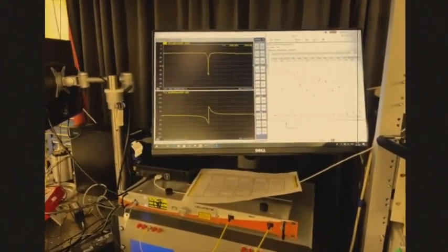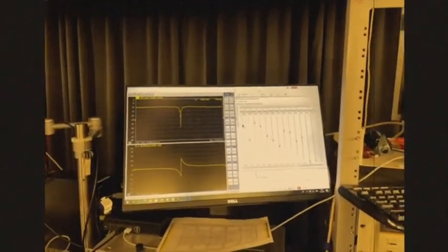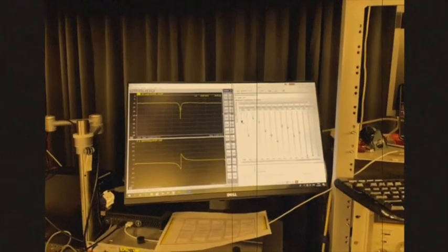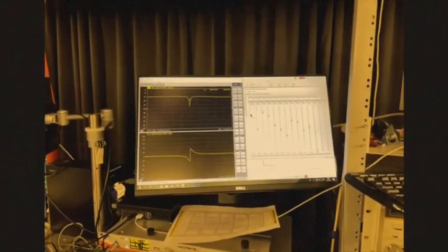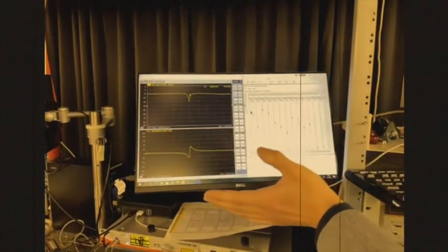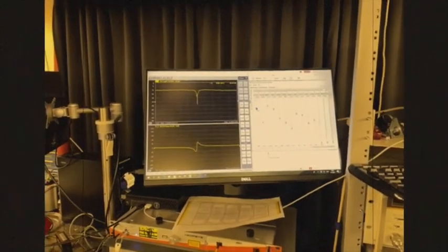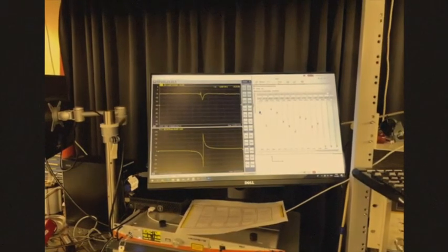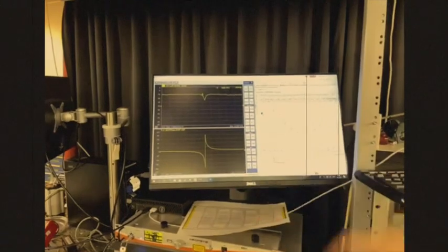And we can see if we change the coupling of our ring resonator, we can change the amplitude response and also the phase response. You see, now the notch becomes shallower and shallower. This shows the potential of the reconfigurability, or the programmability, of our photonic chip. Also, we can set this chip in another state, what we call the overcoupling state. You see, the phase response is very different from the previous one.